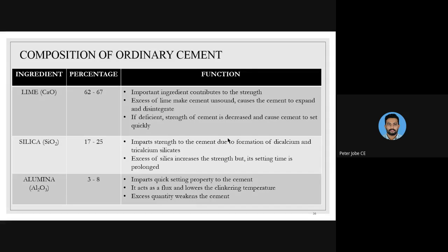The setting of cement is actually controlled by calcium oxide and the reaction with water. So it's always necessary to add the optimum amount of water. The water should not be too much, or too little. If it is too little, the cement particles will not get enough water to set, this changes the property, and it won't make a good mix. And if the water is more, it can cause some of the cement particles to just wash away. So the optimum amount of water should be maintained.